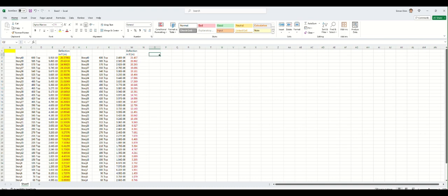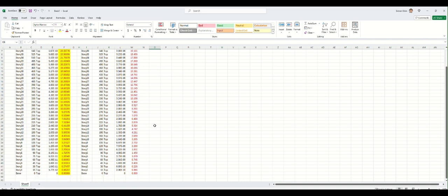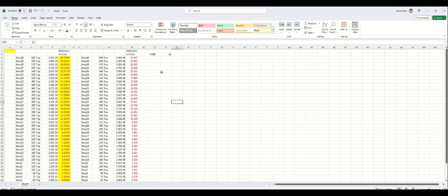h over 400, which is 600 feet times 12 divided by 400. So we're gonna continue to do this until we meet it at the top, with 18 inches. But since this wall is already thick, we maybe think about a better, more efficient way to increase the lateral stiffness instead of just increasing the wall thickness, which uses more material and is not efficient because eventually it increases the foundation wall reaction. So this is iteration.